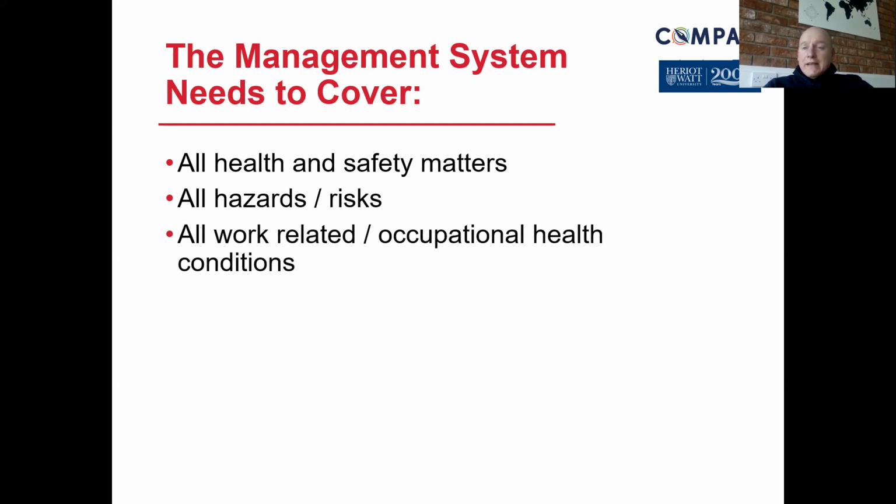Think about occupational health conditions and then related conditions as well, in terms of how they can affect people and their way of life. Again, it pulls back to the hazard risks that were posed and discussed earlier. So you might have, under COSHH, for example, that flour dust again, and then rather than thinking of the explosion risk, now you start talking about the occupational asthma resulting from being exposed to the flour dust.